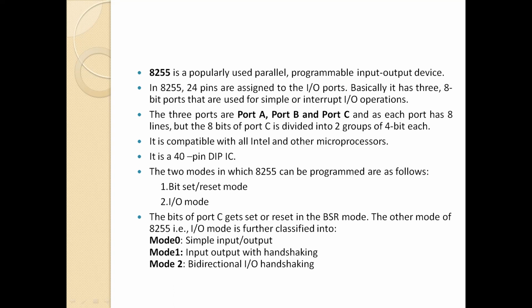It is a popularly used parallel programmable input-output device. It consists of a 40-pin IC chip, and of those 40 pins, 24 pins are assigned to the input-output ports.